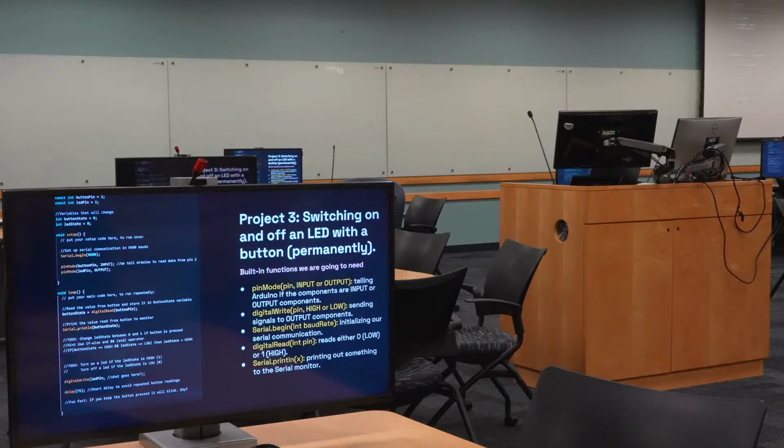Well, actually, in this state, you could still do this project. So you need to tweak the logic. When it's high, instead of just setting high, you just need to change the variable, and then read, or do, for example, digital write, and then it would be the LED state. So you just need to make the logic change the LED state, and here you pass it the LED state. Try it.